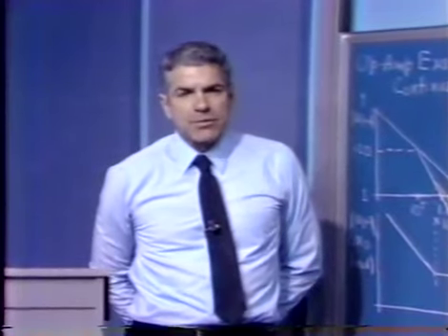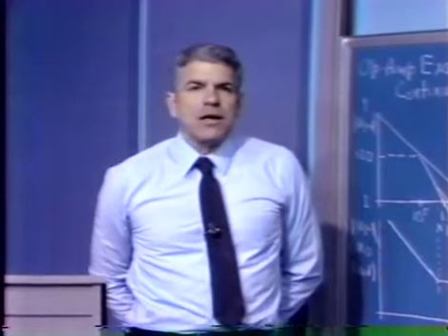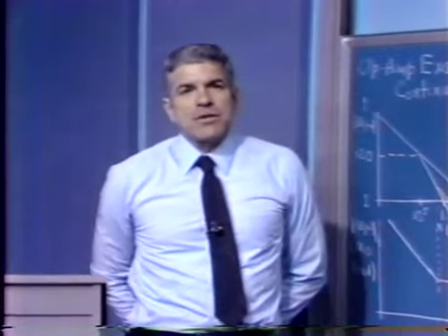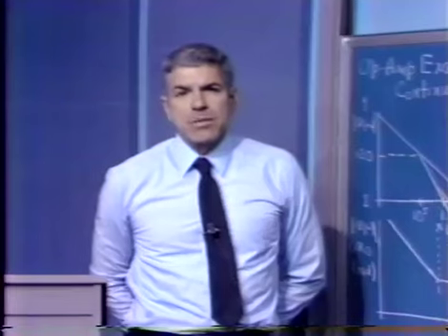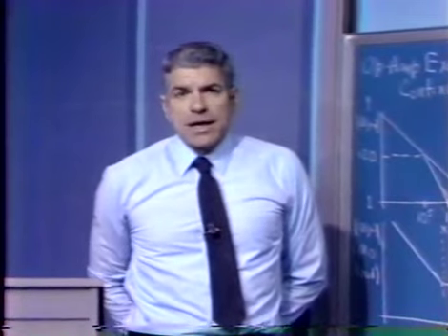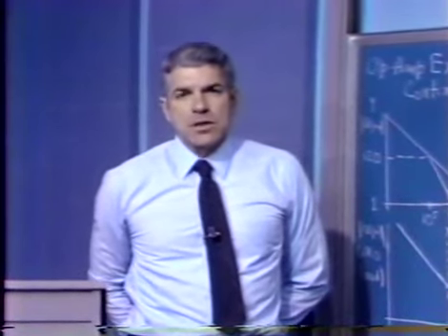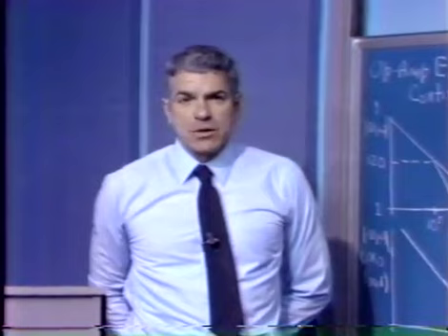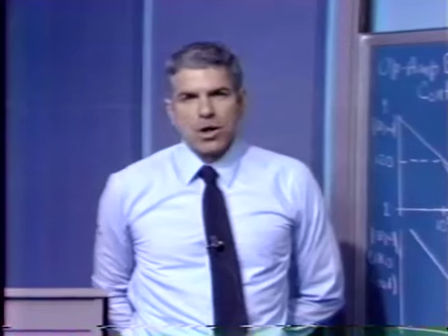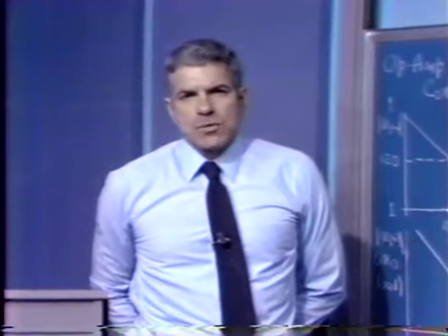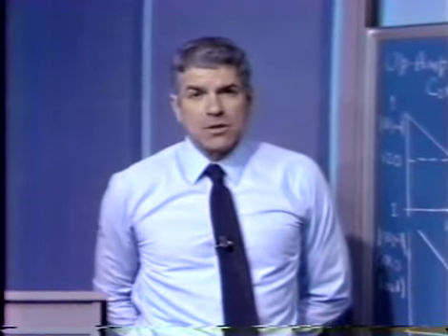Incidentally, this is of more than academic interest. There are certain elements which in fact have dynamics that vary as a function of conditions. For example, a very simple example is that of a power supply. Again, if you build a power supply into some system, people go ahead and connect loads to the power supply. Very frequently those loads include their own decoupling capacitors. Consequently, you can add a great deal of capacitance to the output of the power supply. You don't necessarily know the exact amount. You can put a lower bound on it by including some capacitance internally, but you're never sure what the total amount of capacitance is, how large the load capacitor can be.